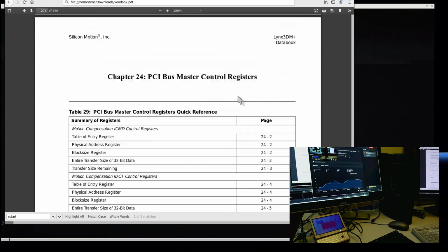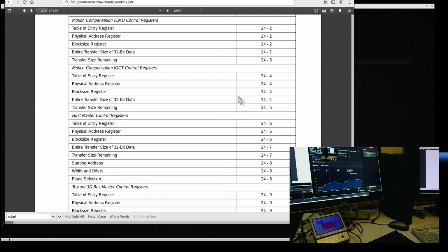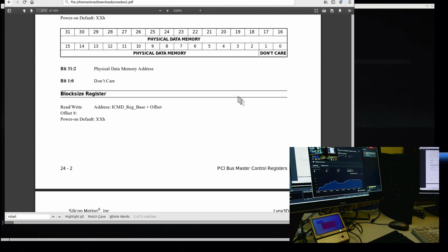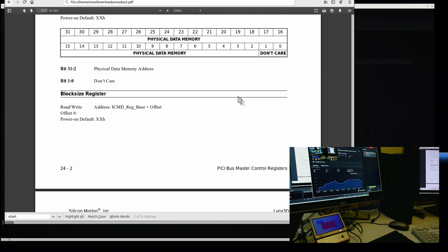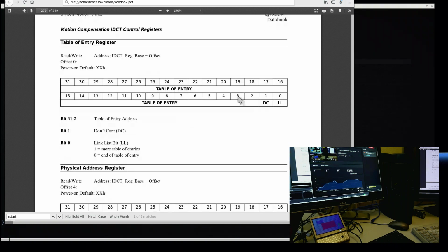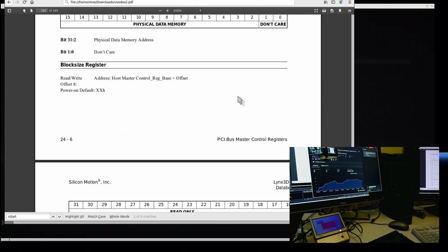And where would this even be right now? Somewhere scrolled. Motions, this is motion compensation. This is DMA. DMA is also a little bit under-documented, so there is some DMA stuff that sounds reasonable, but the format I'm not really sure. If you want to use direct memory access to BitBlt to transfer a whole block of vertex data, you would need to trial and error the format. It's not really documented, so not really sure how long that would take.